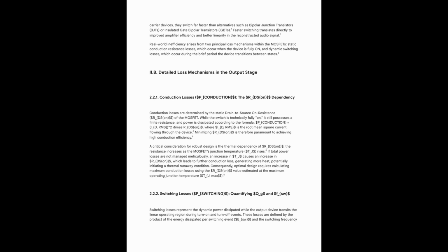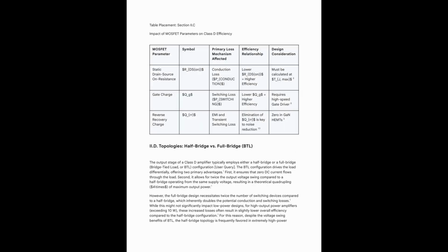That's huge. It is. And think about the thermal impact. Less waste heat means less heat to get rid of. A 90% efficient Class D amp makes only about 1/5 the heat of a 50% efficient Class AB one. 1/5. So that explains why they're so much smaller. You don't need those massive, heavy heat sinks anymore, or maybe none at all sometimes. That's the geometric advantage, yeah. It makes them practical, portable. You can put them anywhere. That change was critical.